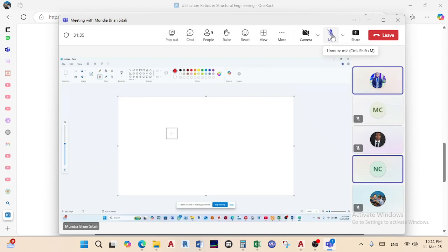All right. So in this case, maybe the reason why we don't want to have more than 600 by 600 is because that's the only allowable size that the architect has proposed. So you provide other measures in trying to reduce the loading that is going to your column, essentially reducing the dimension of the column.